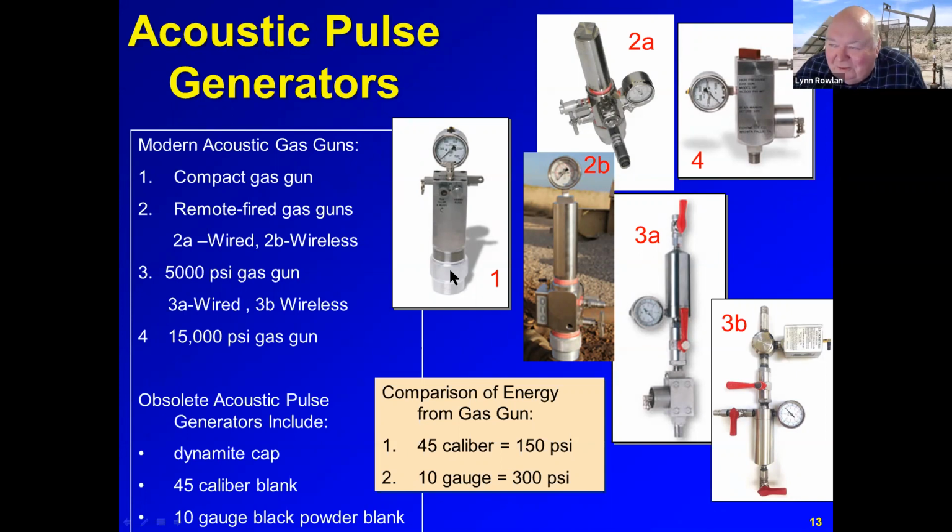Now, when you shoot a fluid level, the change in pressure is the echoes from the shot being fired. Any change in the wellbore diameter, like a collar or a tubing anchor or perforation or liquid level, can all make echoes. So when you shoot this pressure into the well, you push on the gas at the surface, and the pressure from the gun travels down the well and echoes back to the microphone. That creates an acoustic trace.